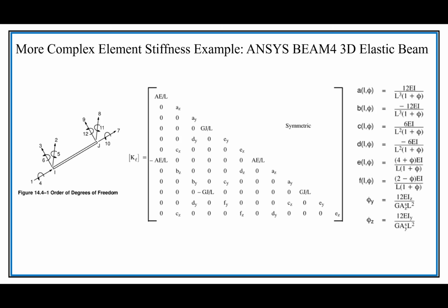And now, if you can imagine, for a thing that has a lot of complexity, there's going to be a bunch of different beam elements. You wouldn't just use one beam element between two transitions. You use several beam elements. You can imagine how big the stiffness matrix gets very quickly for a combined degree of freedom problem that could be pretty difficult to solve.